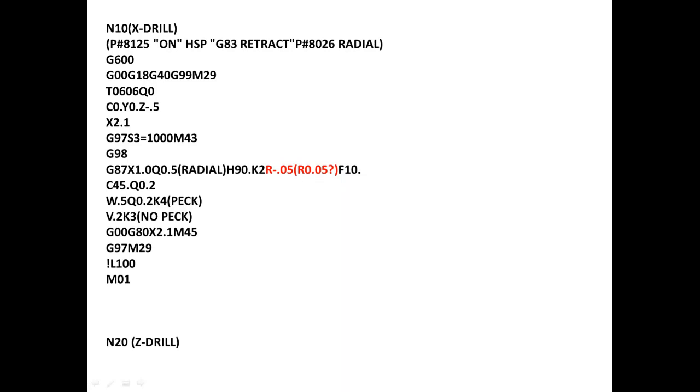Yeah, so G899, let's say you didn't mill the main spindle size. So let's say you have a hex material. That's not going to be the C0 on sub spindle, maybe not even C0 on the main spindle. It's going to be odd position.